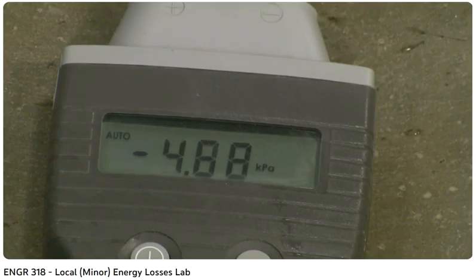Now, I did turn off the bench for just a moment, but I didn't change any of the valve settings. I left the bench flow setting the same. All the valves are as previously, and so we will assume that the flow rate is the same as was quantified previously. So now this is the final fitting on pipe path A, gate valve, item number 21. So measure the pressure difference there.